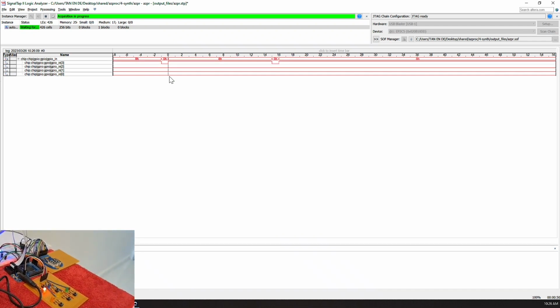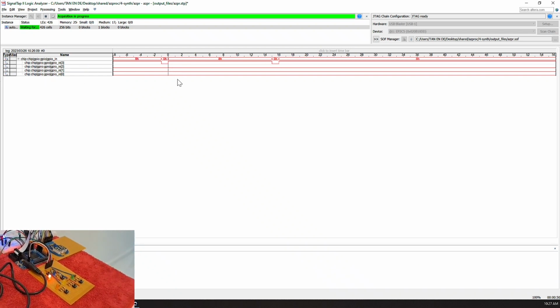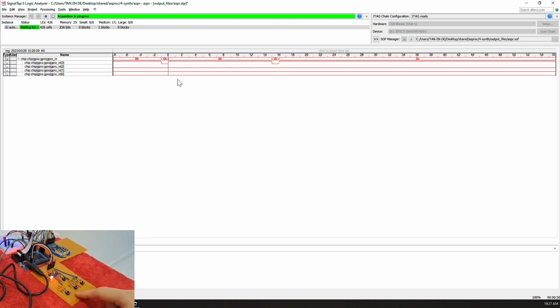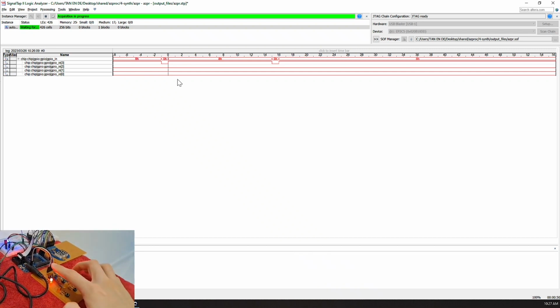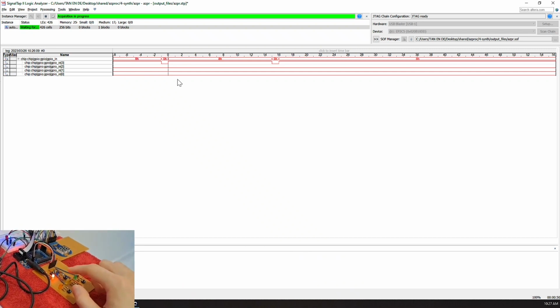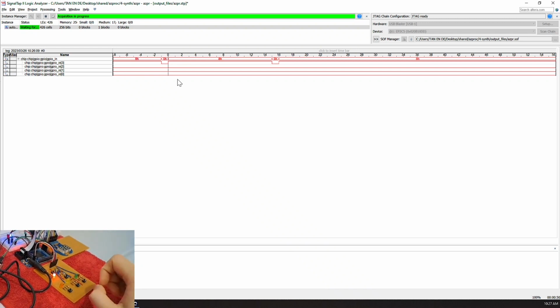And by the way, the reason we are seeing more than one rising edge from the GPIO in is because this hardware design doesn't have proper debouncing using the Schmitt trigger input. When I purchased this FPGA, I was expecting it to have Schmitt trigger input configurable at the pins, but it turns out that there is none.